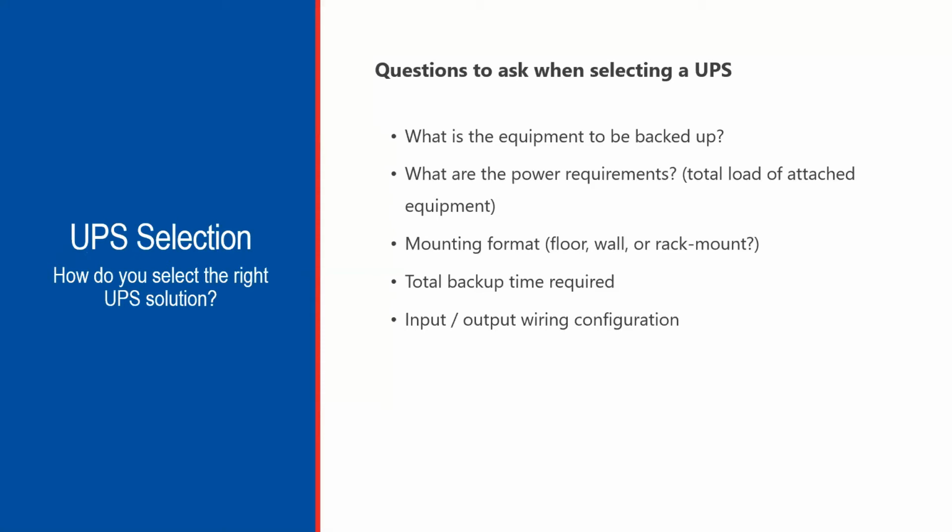So some of the key questions in order to properly select a UPS do need to be answered. And there are 5 primary questions that you do need to get accustomed to asking, or should ask, before selecting the right UPS. The first being, what is the equipment to be backed up? This helps to determine how vital it is to the company operations.